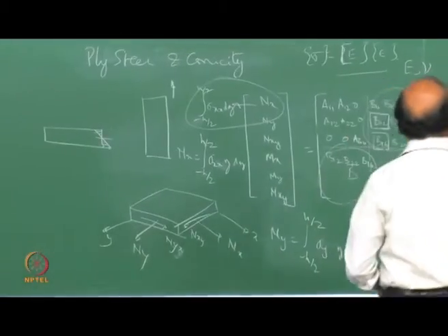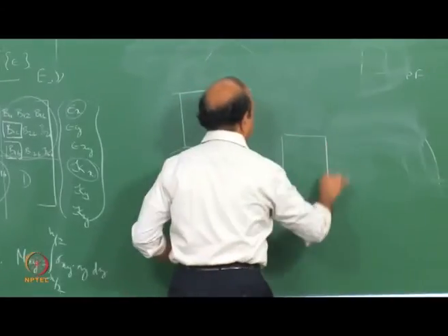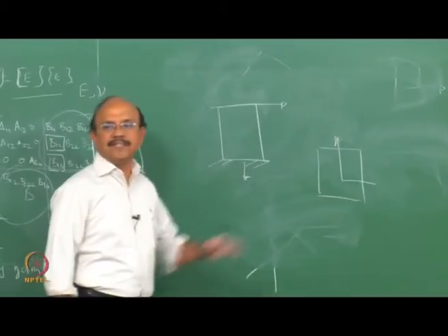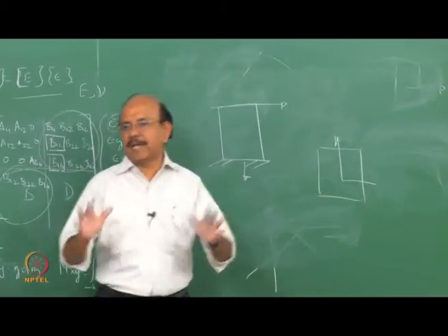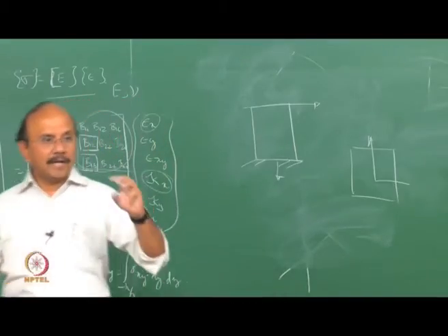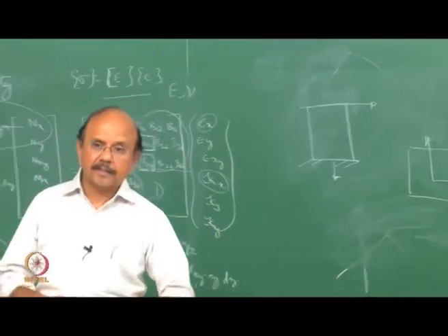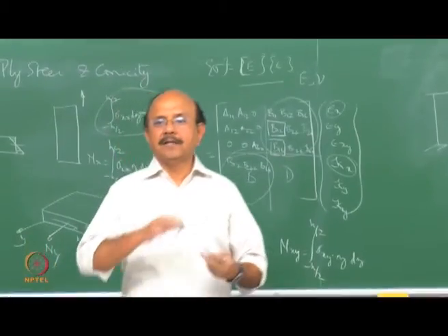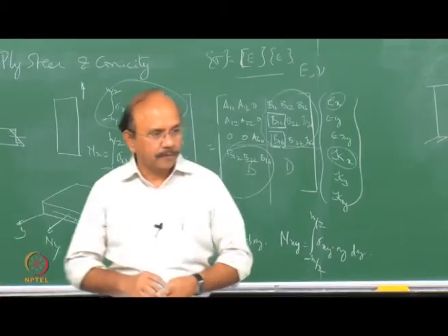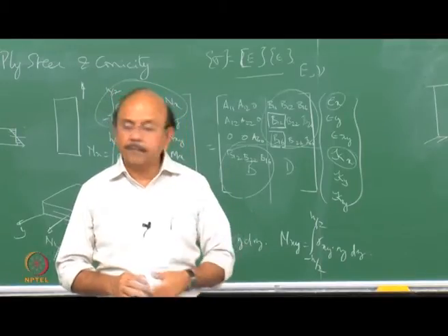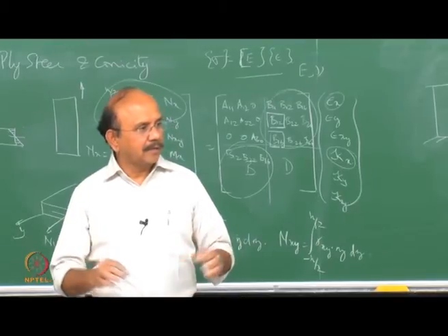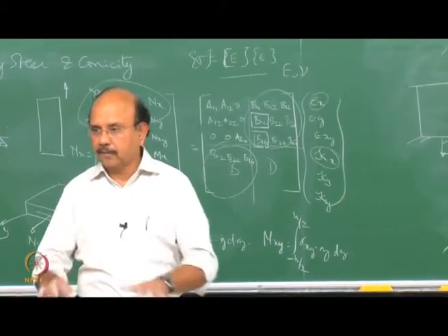So if I now have a block whose plan is like that, and I have symmetric axes, it is symmetric bending. It's a simple cantilever beam that bends. But of course, it's not a cantilever beam as you have studied it, because it is a short, fat fellow. Hence shear deformations become very important. There are other things happening, and the simple cantilever beam theory you have learned cannot be applied. That's one thing.